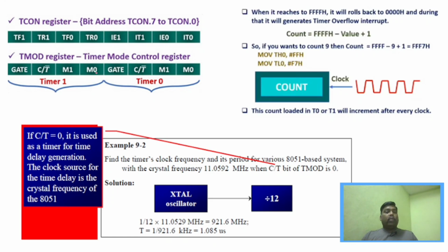First thing is we know what the TMOD register and the TCON register are. In the TMOD register, you know that this is timer 0 and timer 1. In almost every program we normally select only mode 1 operation, because we can create the maximum number of delays. If it is mode 1, we have to make this bit 0 1. And if we are going to use timer 0, we have to select this particular bit, so it is 0 0 0 0 0 0.